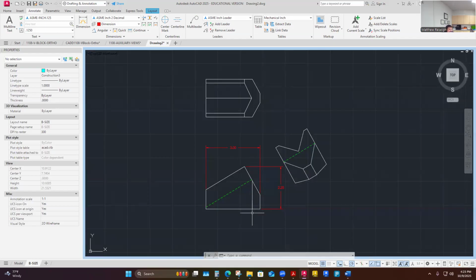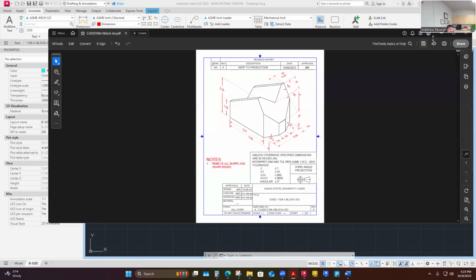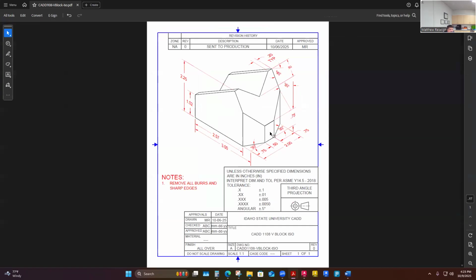and not top down. I've also added this one, and that makes me think, am I going left to right or right to left? I don't know yet. I don't know which is my best, but either are decent surfaces. Oh sorry, I did have that up, but I wanted to go back to the isometric view of this thing and say that I don't think it's wrong to use this surface right here as a datum, and pull dimensions from right side to left. Or should I use the left side where it appears as a surface there? Should that be where it appears as an edge? Should that be where I pull dimensions from left to right? At this point, it's arguable either one. I don't know which one is better.